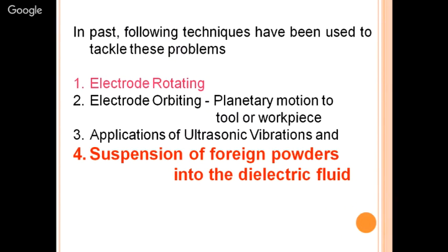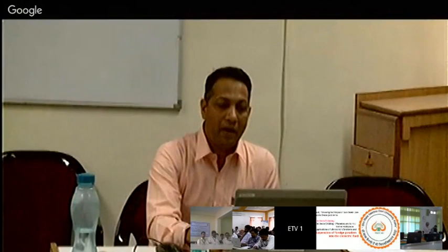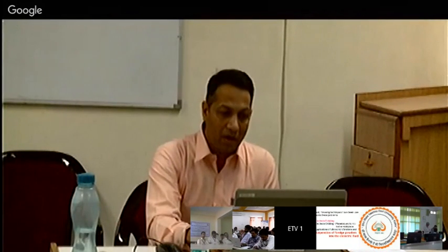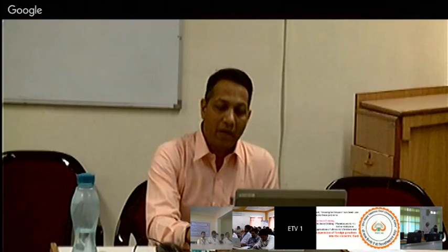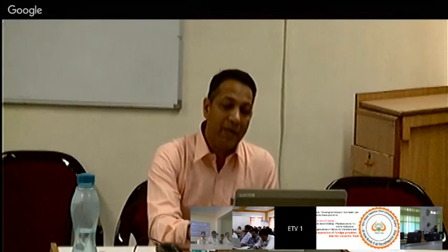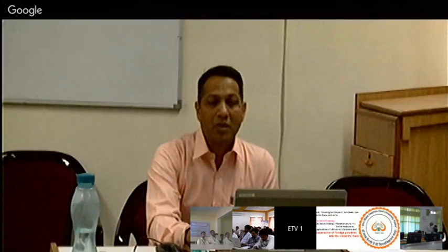Some have given rotary motion to the electrode, some have given orbiting motion to the electrode, some have given planetary motion to the workpiece. The purpose is to clear the gap. Many have used ultrasonic vibration, and many have suspended some powders into the dielectric fluid.